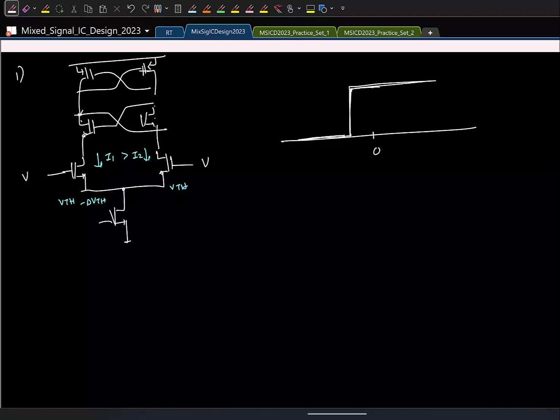And it turns out that if you take any two transistors which are supposed to be identical, you know that there is going to be some mismatch in each of these properties, and the standard deviation of this mismatch is inversely proportional to the square root of the area. Okay. So this is called Pelgrom's model or Pelgrom's law. I'll just directly give the result.